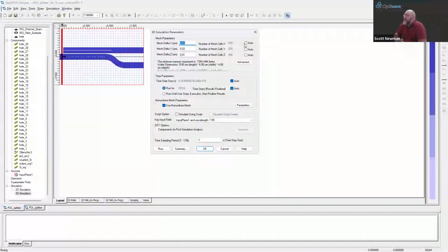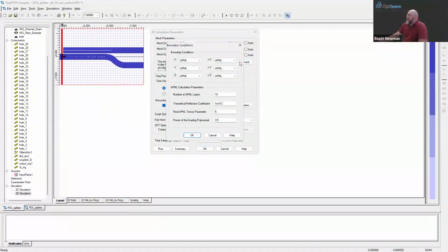But as you would imagine, considering for the through waveguide we're using sub-wavelength geometry, 1/10 of a wavelength probably is not a high enough resolution. So you remove the auto setting and then you can specify your own refractive index spacing for your mesh. Under advanced, we can control our boundary conditions. For most applications, customers typically use our perfectly matched layers, which is what this one is set for here. But you could also use our electric conductor, magnetic conductor, or the periodic boundary conditions.